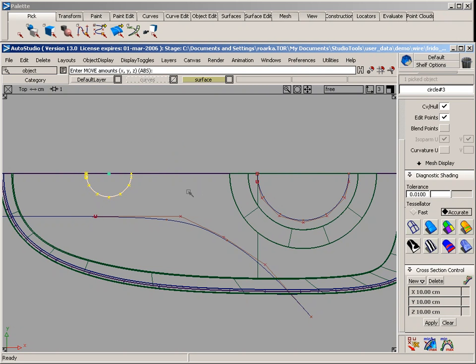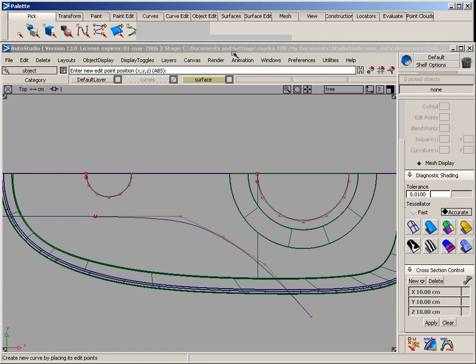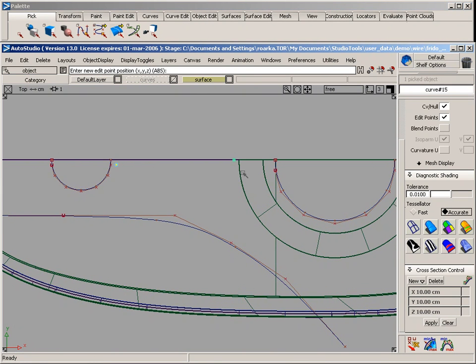And now I'm going to decide to maybe create some sort of a geometry or design that connects these two. So I'm going to bring out another curve using edit points that I'm going to start somewhere over here, and with the middle mouse button bring a curve over to this end. Now the problem with this is I want these all to be connected and to be one.